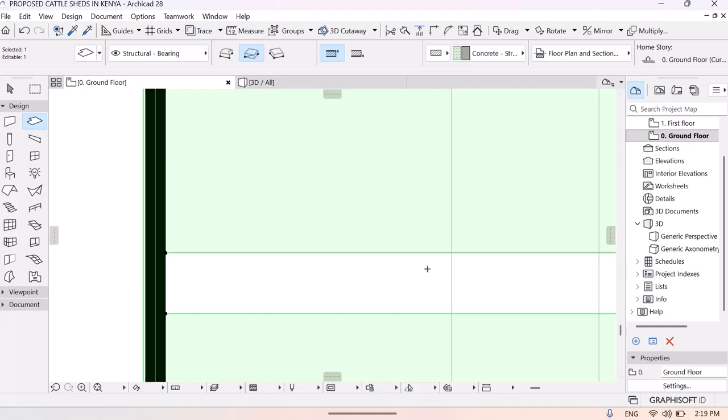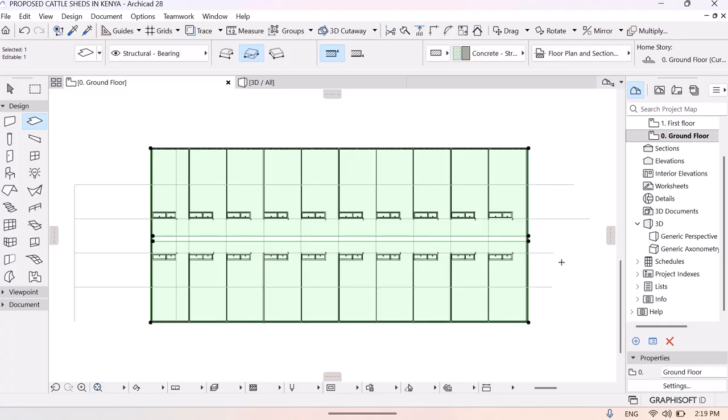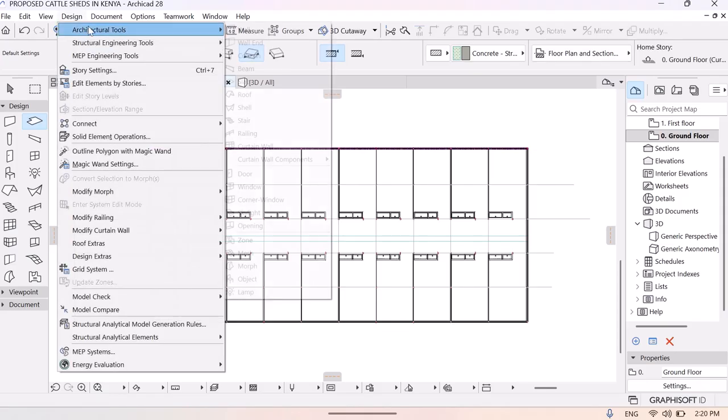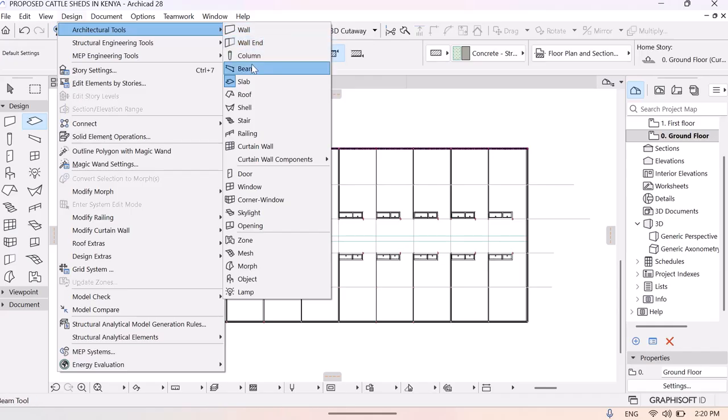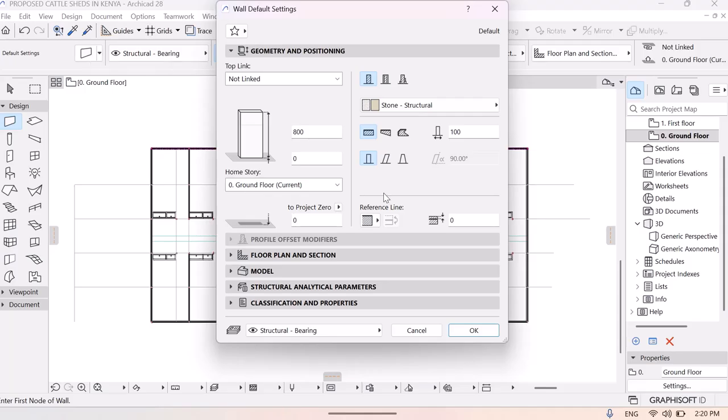As you can see, we already have our drainage system. Let me just zoom out. There is our cut. The next step should be a wall, some sort of retaining wall, to help in draining the water. I normally advise that natural stone or concrete is quite useful for such works, because natural stone walling does not permeate water or moisture.